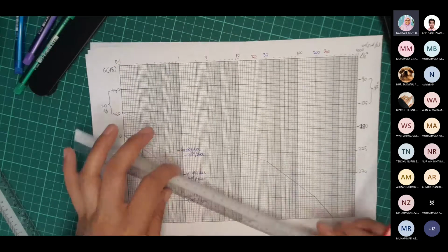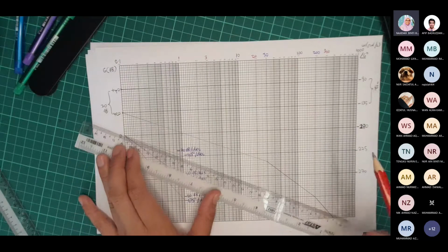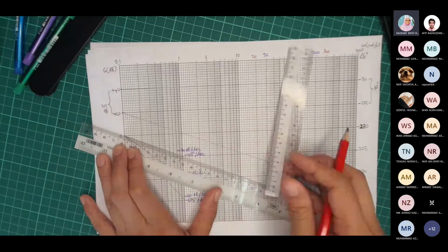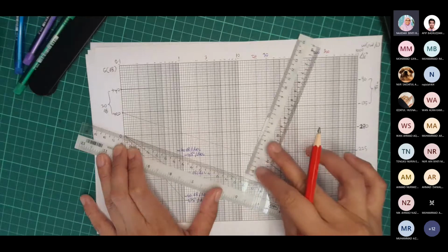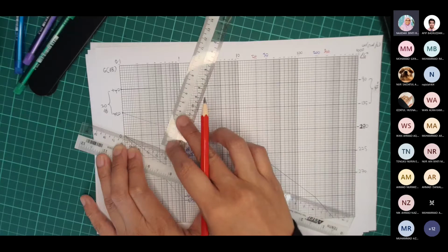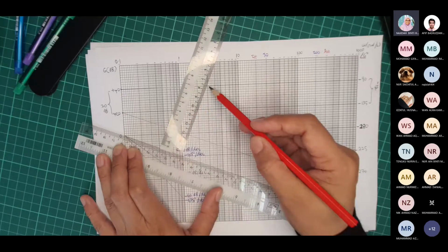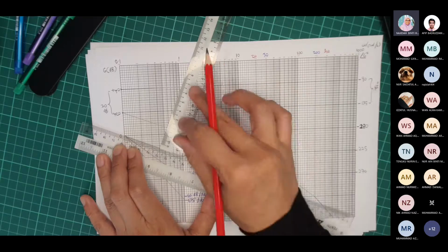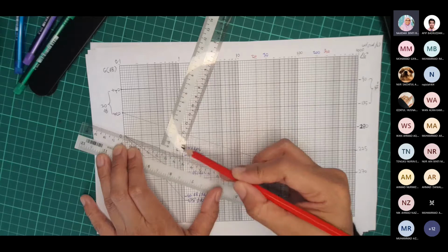So now I want to refer to my -45° per decade slope for my first ruler, and then this is my second ruler. I make it perpendicular to the first ruler. I move it to the point where I want to continue my phase plot, at 3 radian per second until 30. It should be negative 45 degree. So the second and first ruler must be perpendicular.